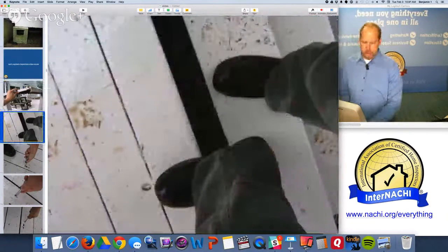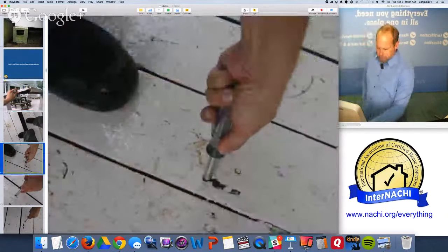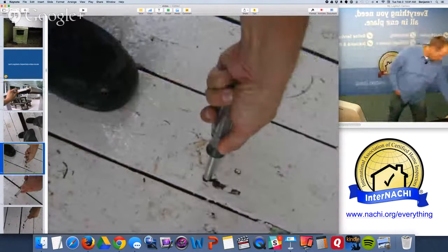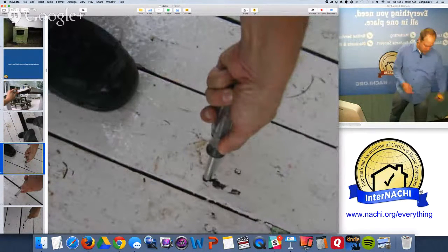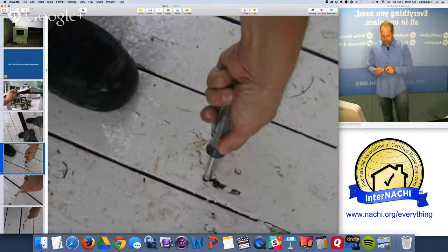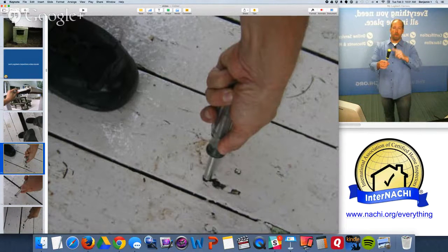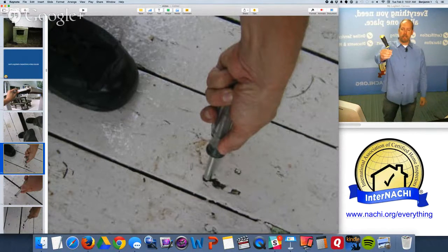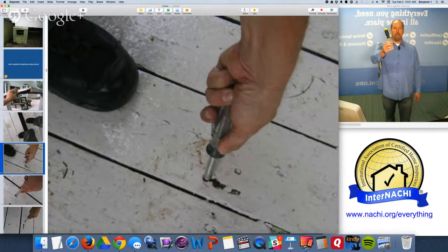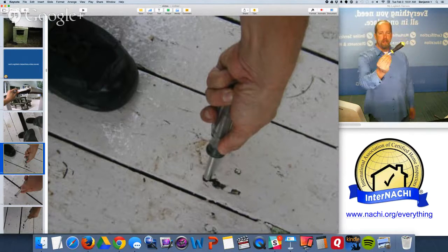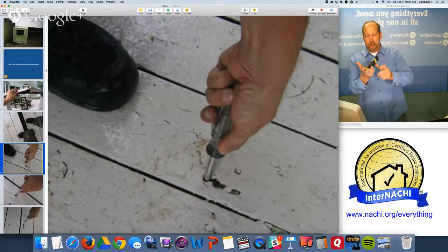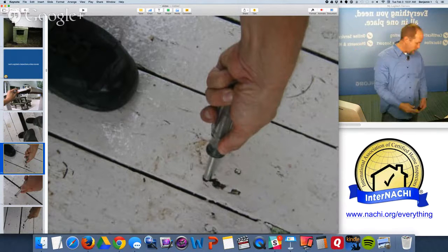So the railings are in poor shape. The steps are in poor shape. That's my screwdriver. I went over all these tools here, but that's my screwdriver going through. When my screwdriver goes through, I don't try to hide it. I take a picture of it, and I put it in the report. So anything that I damage like that, that's a good thing because I found it for my client. So when my screwdriver goes through something, I'm taking a picture just like that.